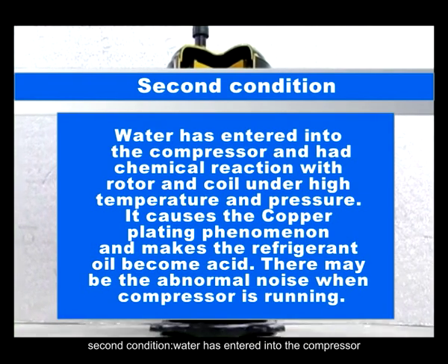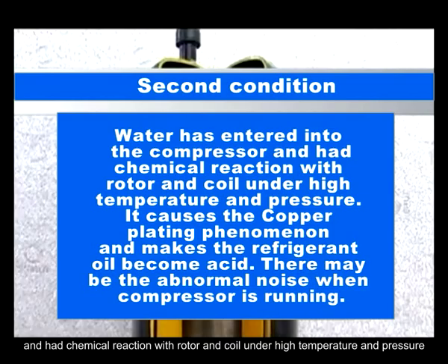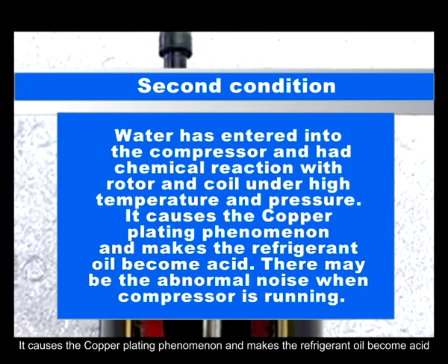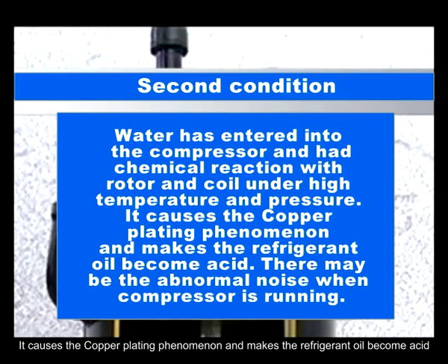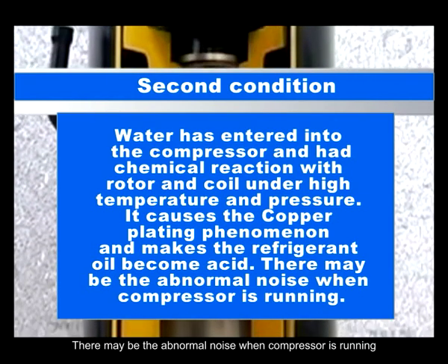Second condition. Water has entered into the compressor and had a chemical reaction with the rotor and coil under high temperature and pressure. It causes the copper plating phenomenon and makes the refrigerant oil become acid. There may be abnormal noise when the compressor is running.